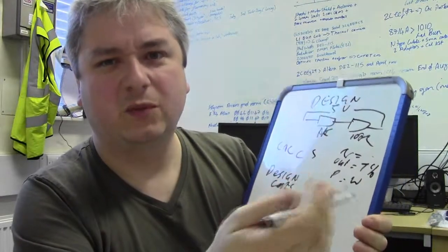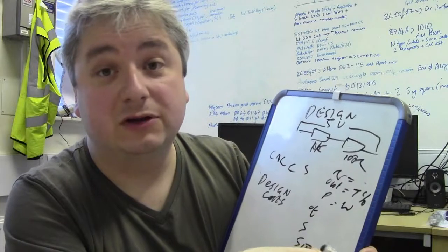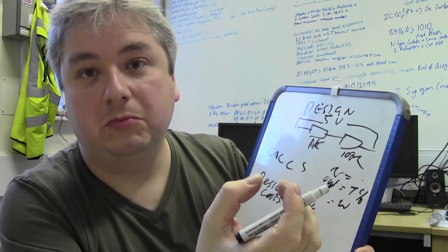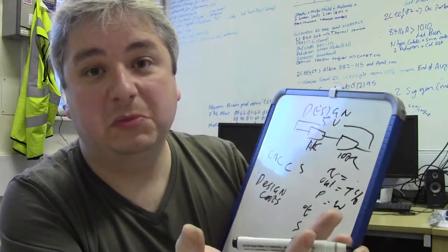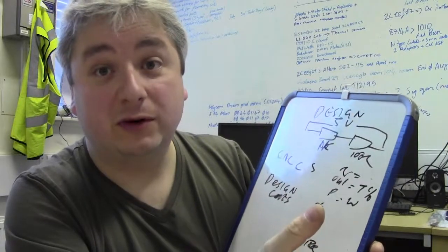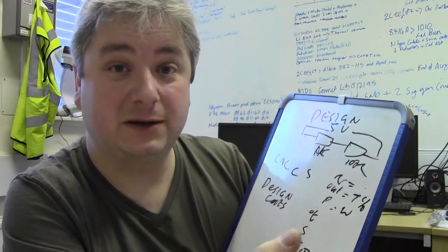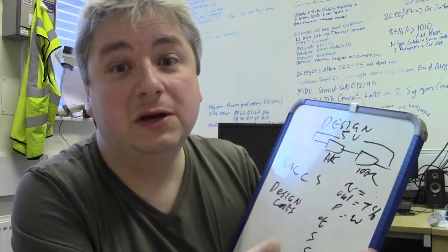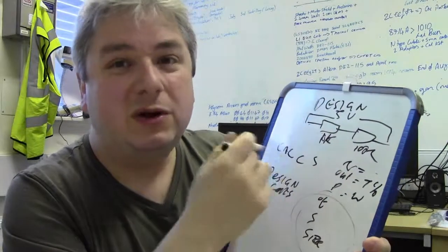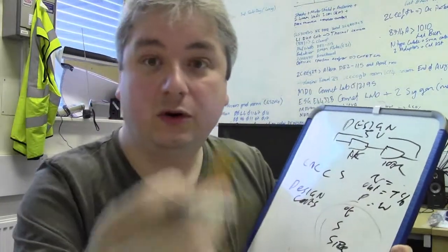Stability is all about what kind of situation, what signals are passing through your resistors. Is it AC, is it DC? Do you have lots of transient signal, things like that? Will a picofarad of stray capacitance affect your circuit? Will a microhenry of inductance, or fractions of a microhenry, depending on what you want, affect your signal? Is it a filter? Is it a tank circuit? Is it a filter circuit? Is it for a charge pump or anything like that? Are these other things going to affect it? And that all goes into your design. It's all part of your design constraints, and that's how you pick out which one you actually need.